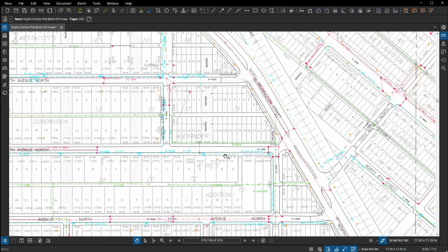If I do a Control Shift V, it drops that in the exact same spot it was copied from on the other page. That could be key if you're trying to make sure you line things up from page 1 to 2 to 3, whatever you're going between. Paste it into the same location it was copied from. We'll just Control Shift V. We'll just paste in place.